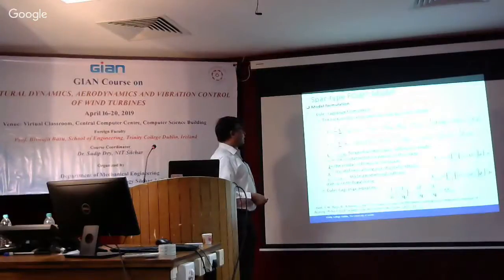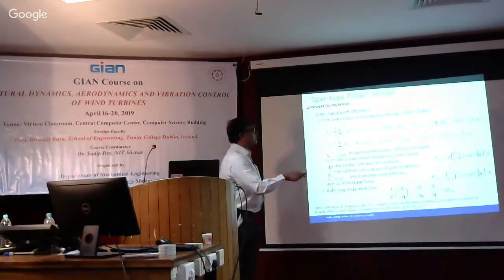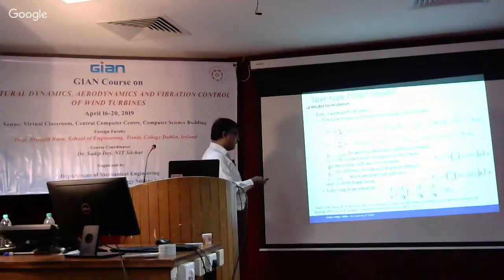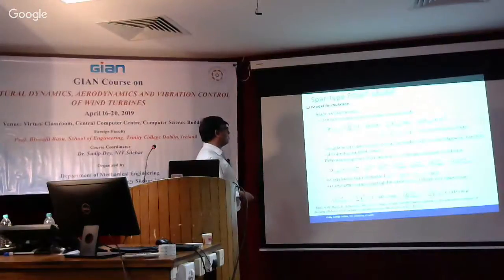And then take the total kinetic and potential energy of the beam, the nacelle, the platform, both the inertial mass and the mass ms. And this is the rotational inertia here because the platform is rotating, so that needs to be added now. Again, the stiffness term is coming from all the conventional terms, but now you have the additional terms for the platform. And with this, now we can actually use the Euler-Lagrange equation to write the equation.